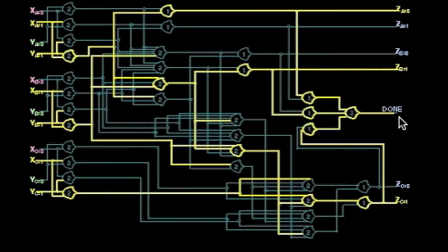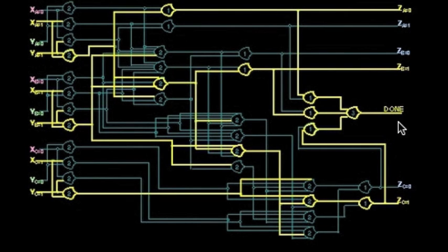Now another thing to look at about this circuit is that considerably less than half of the gates transitioned in generating this correct output. And a lot of the gates had input, but they just didn't meet their thresholds. And we'll talk about those in a bit with the null wavefront. So the done signal says we're done with the data wavefronts. So the done signal goes back to the input of the circuit and allows a null wavefront to propagate.